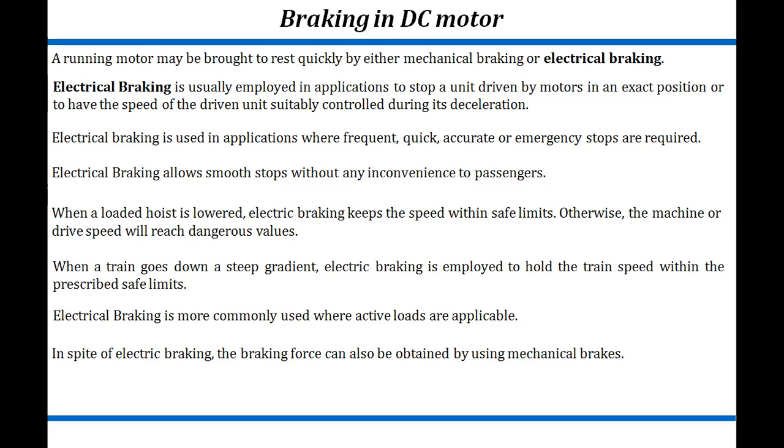Then we have seen about the generated EMF and the back EMF in the DC motor. We call it back EMF in the DC motor because it works in opposite phase with respect to the supply voltage. And it is very much necessary because if we do not consider back EMF, no amount of power will be left to do mechanical work. That's why there is a need of back EMF.